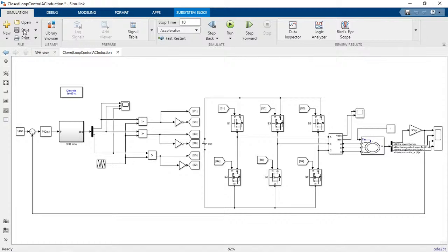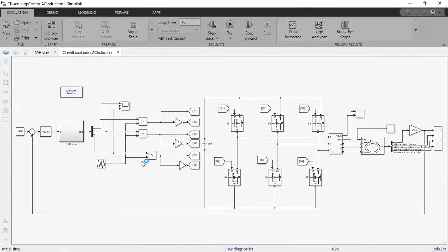By this method, we can get a controlled mechanism for adjusting the speed. Now 1450 is the reference speed, and now I am going to run the machine. Just wait for 2 seconds, it will give you the data. It keeps on running. By this method, we can change the motor speed with our reference speed. In industrial applications, people keep one potentiometer to change the speed. So this is the exact algorithm for that application.